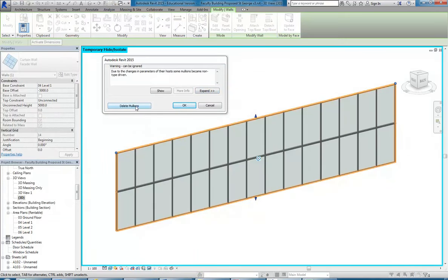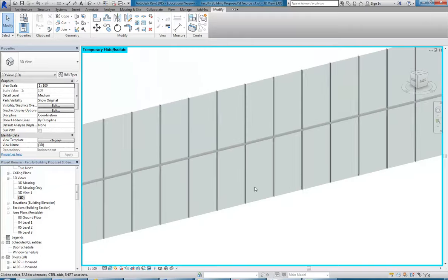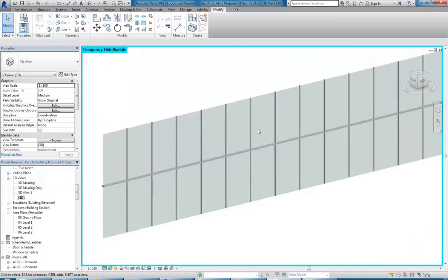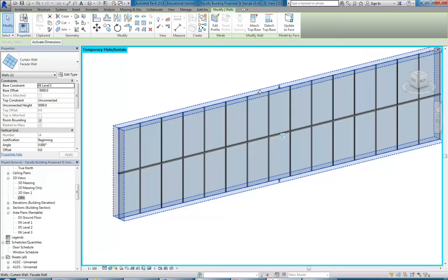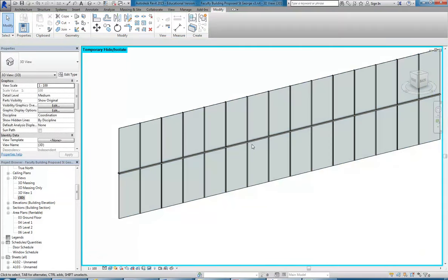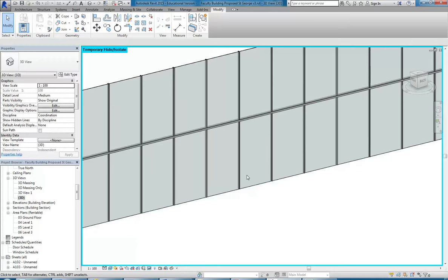And again, it's going to give me the option to delete mullions, so that's okay. I want to delete them. And then I've got the mullions on the edge turned off, which is normally the way I leave it, because often you won't want mullions if you want to have them recessed. Then you just don't show them in your curtain wall, and that's a nicer display usually. So they would still have the top and the bottom plate, but they'd be integrated or cut into the floor in some way, and the roof or probably the soffit. Yeah, definitely show that in the detail, exactly, just 2D rather than trying to model it all 3D.